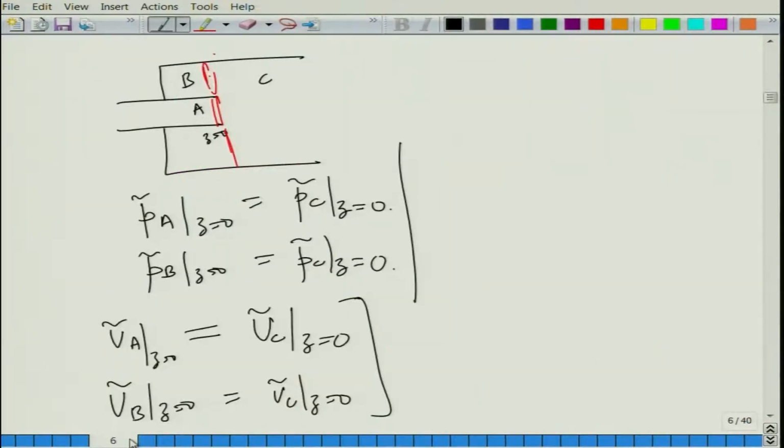multiply, we will basically do some sort of mode matching, exploiting again and again three-dimensional analytical things, wherever you have a mode matching or a piston driven model or a Green's function model, wherever one has to incorporate the three-dimensional effects without resorting to a full 3D analysis, without completely discretizing the 3D continua into finite elements, rather just working on the two-dimensional problems.